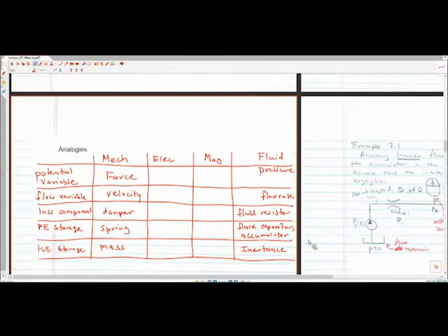Okay, so did anyone go to a super old high school that had clanging pipes? One person went to a super old high school like mine, too? Okay, so in the wintertime, if you ever heard the pipes clanging like crazy, that's actually because of poor fluidic system design. You probably had radiator type heat, right? So you had a boiler in the basement, runs hot water or boiling hot water all throughout the building. That's why your pipes clang. So anyone who's been in a really old building, they hear this clanging noise. It's from the inertance of that fluidic system.